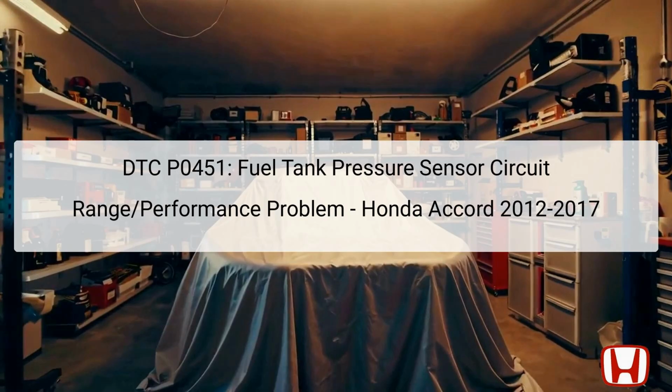Positioned on the EVAP canister, the sensor's output voltage varies with changes in fuel tank pressure. When the engine operates normally, the sensor's output voltage is expected to fluctuate within a specific range as pressure rises and falls.